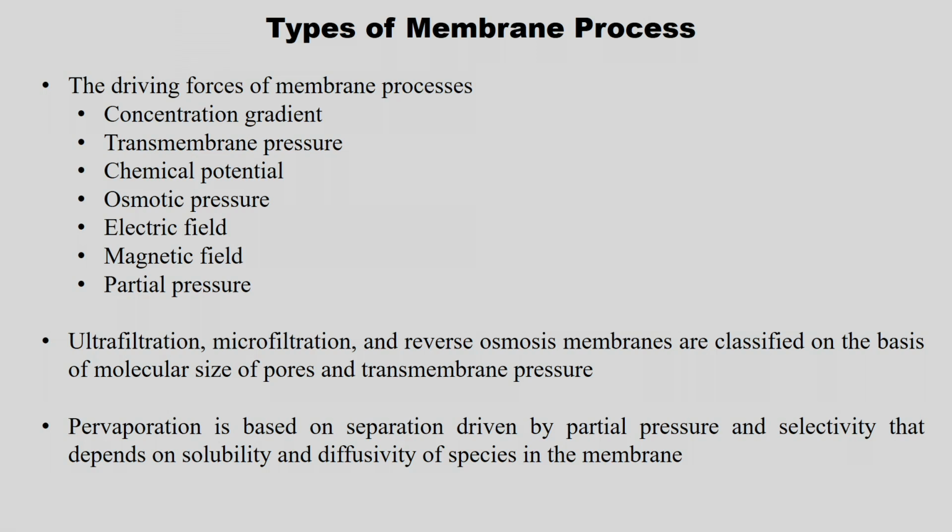And the driving forces for membrane processes are concentration gradient, transmembrane pressure, chemical potential, osmotic pressure, electric field, osmotic pressure in reverse osmosis, then transmembrane pressure and concentration gradient, magnetic field, partial pressure. So, all of them are driving forces based on the particular membrane separation process.